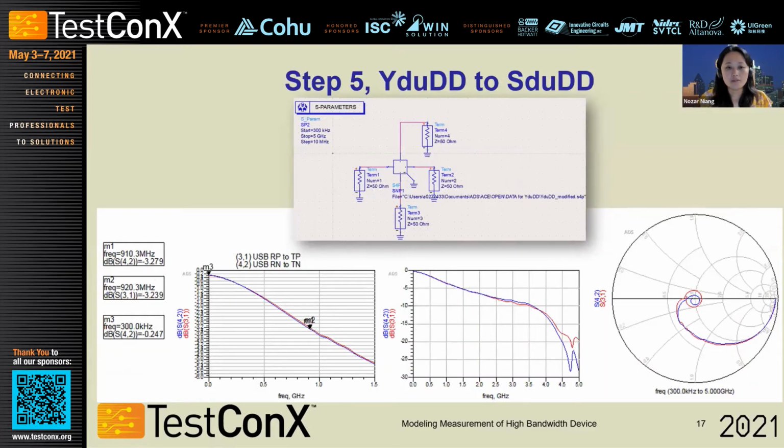And then in this slide, we are changing back to our S parameter domain. This is where you will see everything is de-embedded. It means all this parasitic that we see from the device fixture that we are using are extracted out from that measurement. So you will see that device performance got significantly improved from around 830 megahertz to 910, 920.